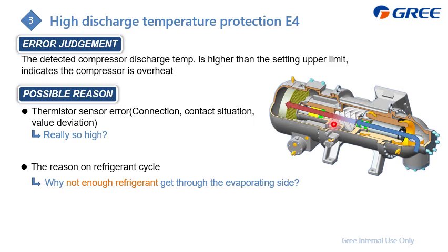That means the inside motor is overheating, and overheating will also lead to the inside oil being decomposed. So to check this error, first of all, you need to check whether the discharge temperature is really so high or not by checking the temperature sensor, and the method I already introduced in the previous stage. And the next is to focus on the refrigerant cycle and check whether and why there is not enough refrigerant at the compressor suction side, which is the evaporating side.